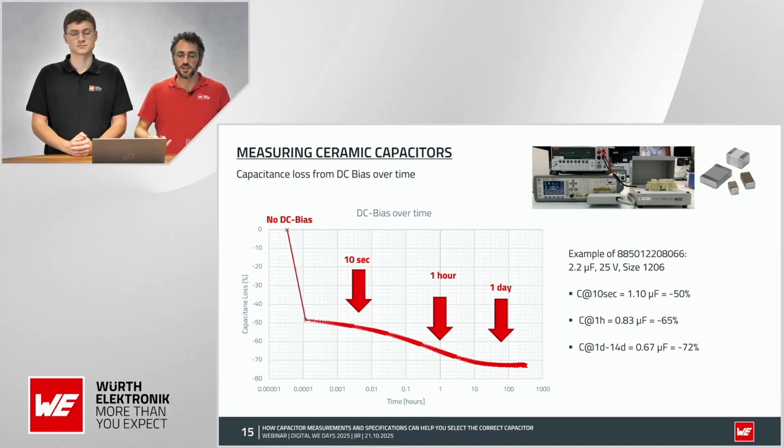For me, it's important that you understand you have a huge uncertainty when you are working with these capacitors. So you have to calculate for a worst case scenario. The curve will never look like this when I measure it for the second time. Every time we measure it, it depends a lot on how long it was on, how long it was off, and how much time passed in between. Did it go to high temperature? Did it go to low temperature? Everything will have a memory effect.